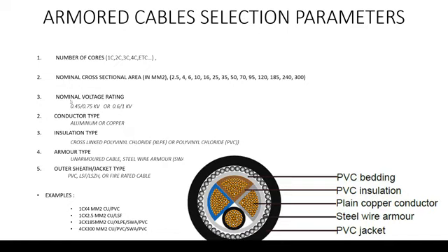Or 0.6/1 kV, which is for the heavy duty cables that can withstand the high current capability required for feeding main feeders, DBs, mechanical equipment, etc. Usually you would specify 0.6/1 kV for all cables. Both these annotations are for low voltage cables only.